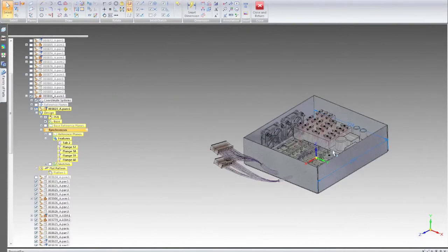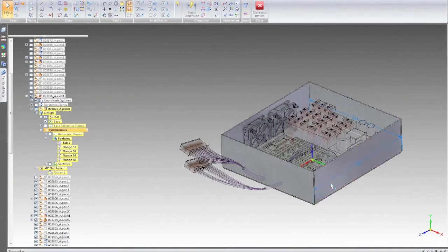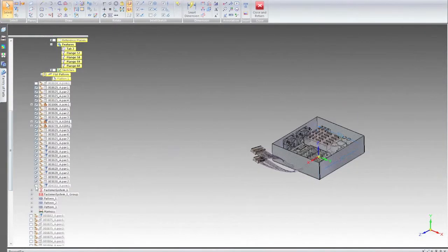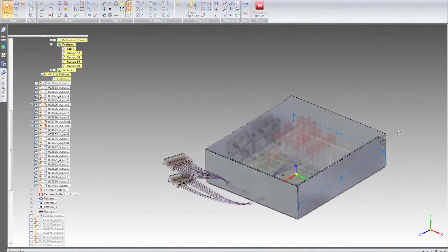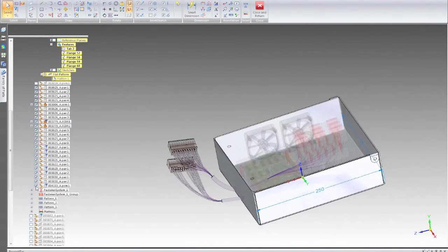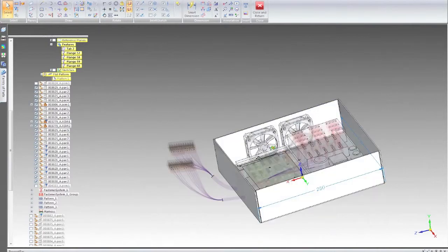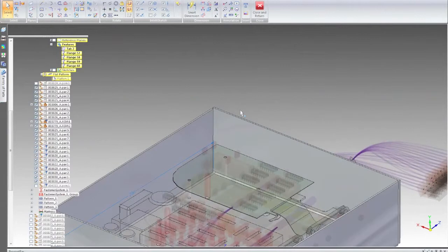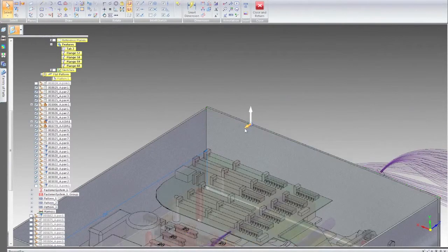Rotate these around. So notice I have a set of fans over here. I got my electrical components, which are already, the base plate already has the mounting holes for it, but I also have a wire harness sticking out of this end, and I will also be dealing with a lid that will need, there's my lid right there, that will need to cover this whole surface area. So notice this lid has 2 holes right here. These 2 holes are for a locking mechanism. So I will need to draw in a tab, and using Synchronous Technology, it's very easy to do so.